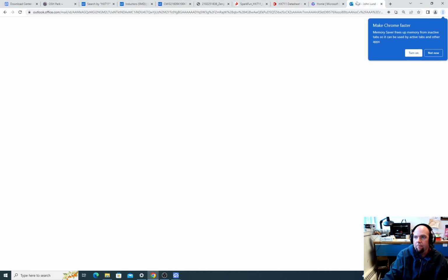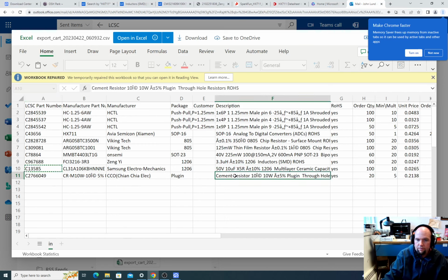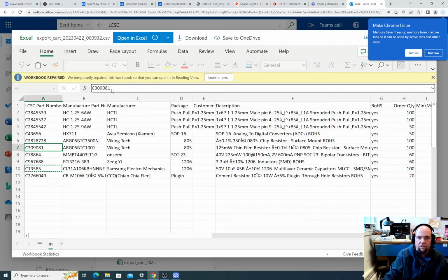So what I did is I bought precision resistors. Yeah, so this is a 0.1% resistor here. This is an 0805 0.1% resistor. I have two different sizes depending on whether you're using a 350 ohm or a 1000 ohm strain gauge. Let's just do one of these though. So we have to copy this.